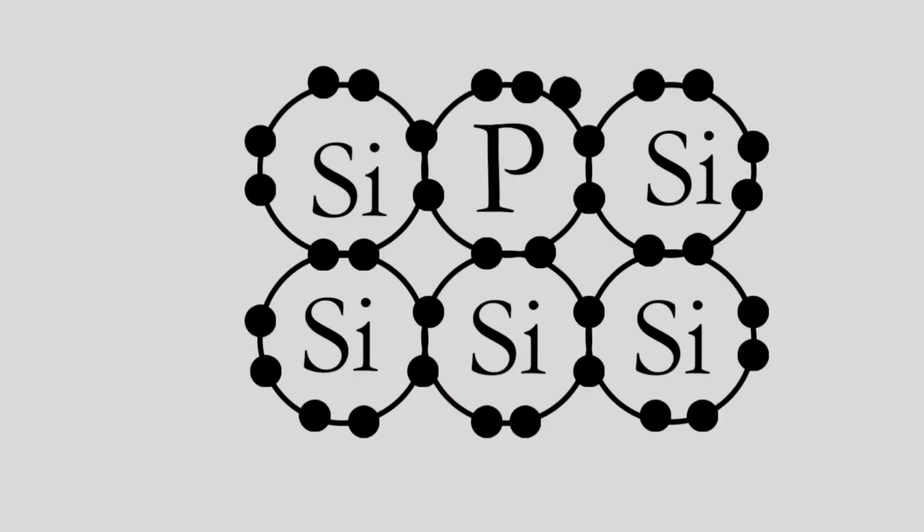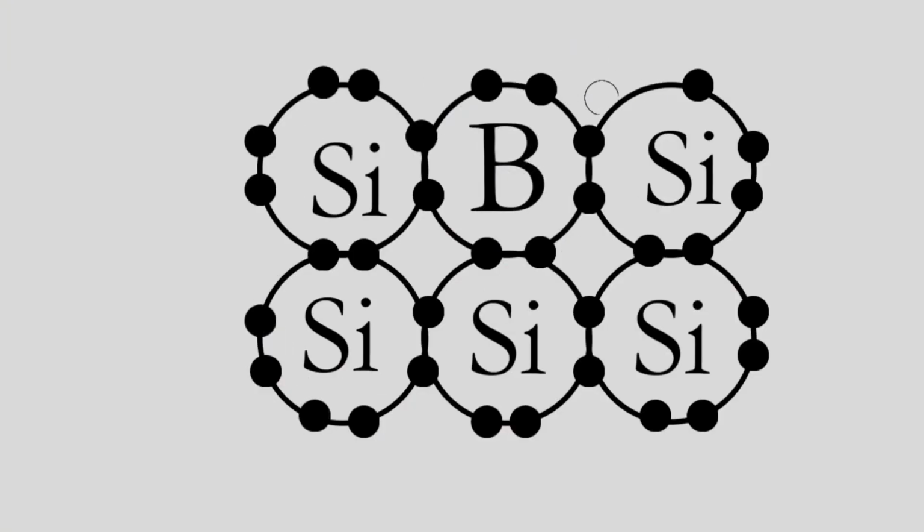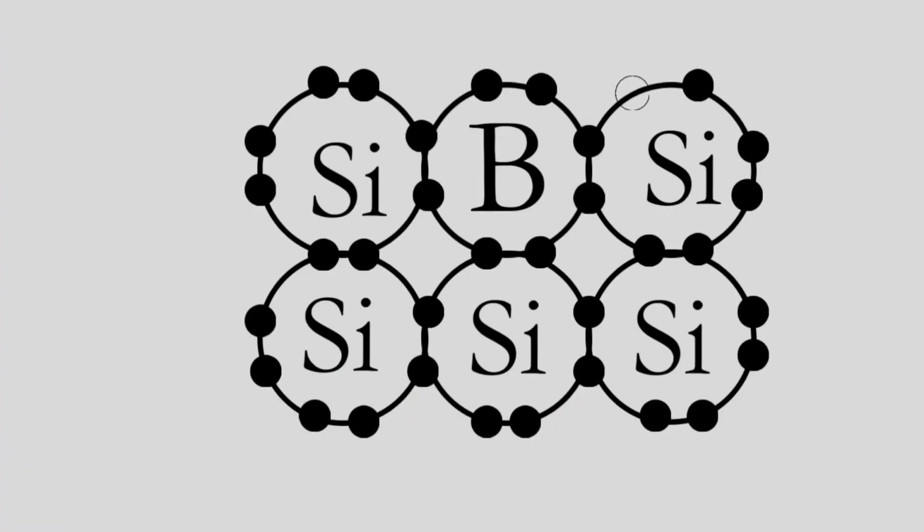To use silicon to make a transistor, if we dope phosphorus atoms, which have 5 valence electrons in the outermost shell, into the silicon structure, we have more free mobile electrons. This is called n-type or negative type doping. If we dope boron atoms, which have 3 valence electrons in the outermost shell, into another silicon structure, there would be one space to be occupied by an electron, so electrons will have spaces to move. This is called p-type or positive type doping.